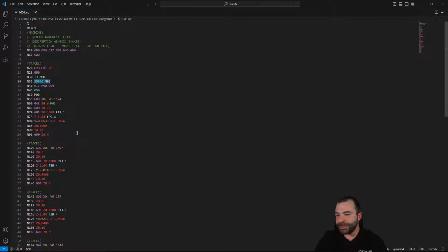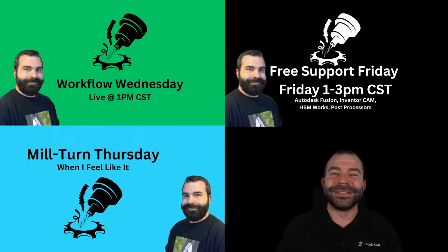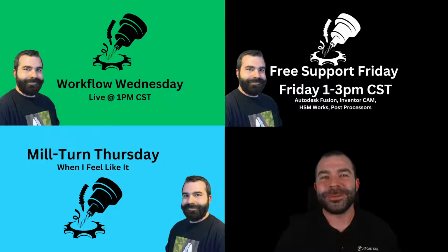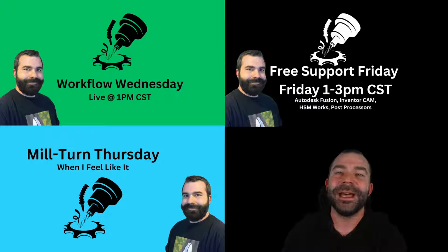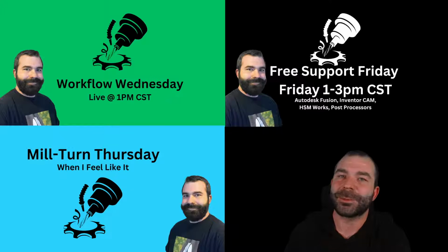So what I'm going to do with that is give you guys the good old-fashioned spiel like always. And of course, none of my hotkeys are working. So let's go ahead and jump over. As you can see, there's a lot of ways to do broaching inside of Fusion. Using that pattern will always be your best friend for creating those cycles. Again, we could convert drill cycles to give you more variables like pecking and all that. That gets much more complex, where you need to reach out to somebody like yours truly.